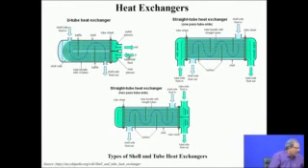So you have some amount of tube side fluid which is coming in, it is getting distributed and will start to flow through these tubes, come to this point, change its direction, and then flow in the reverse direction. They will come to the outlet plenum and will be collected from here. So this is the in of the tube side fluid, and this is the out of the tube side fluid.